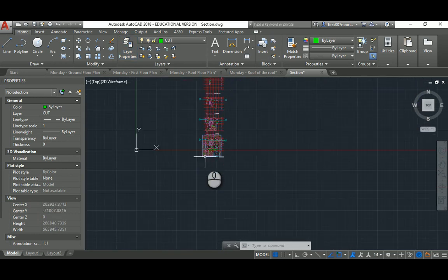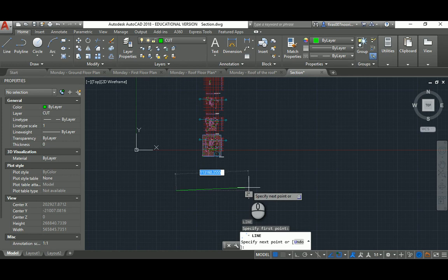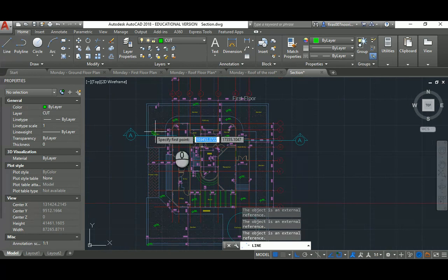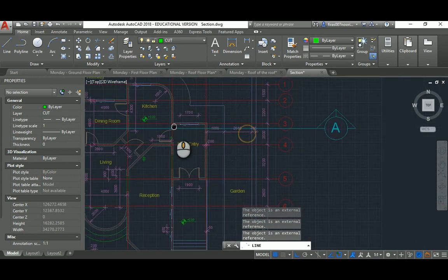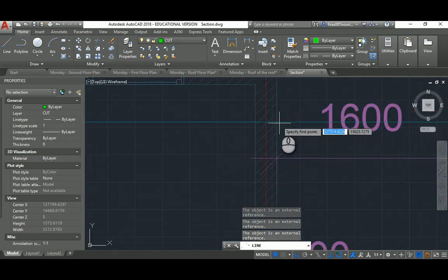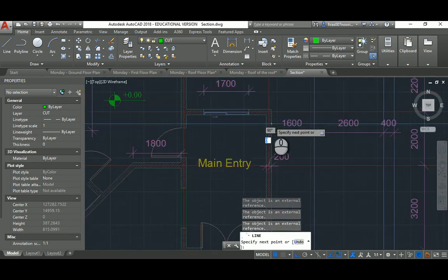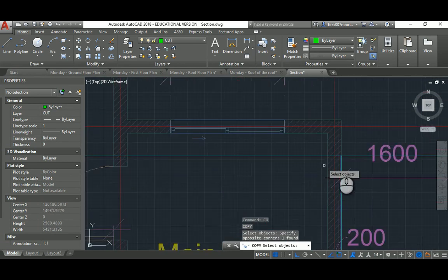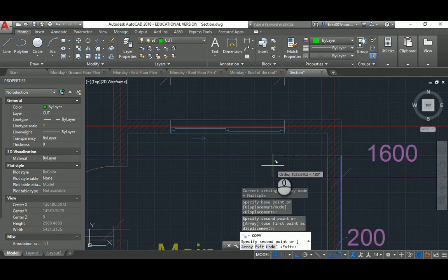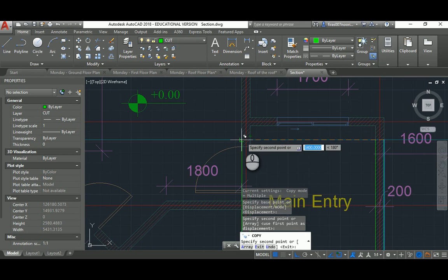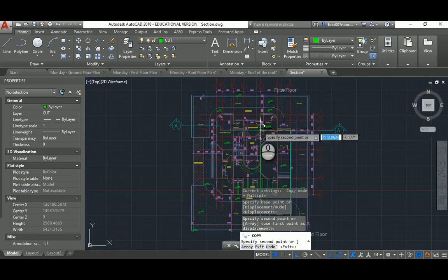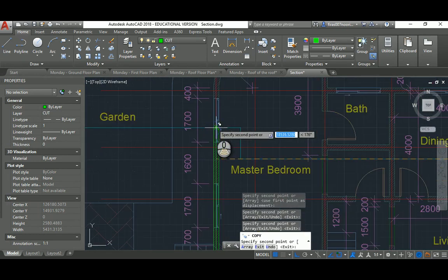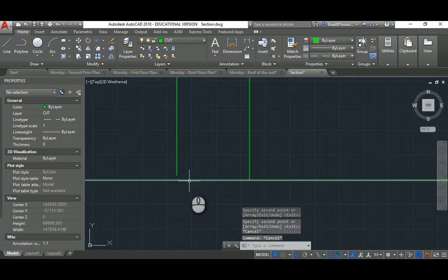Anyway, so I'm gonna just draw a line here. Probably I need F8, and in this case you have to follow and trace the section line, of course, wherever it cuts the building. And in the beginning, that's the technique that I use, which is just to cut the external shell of the building just to define the external boundary of it. I totally advise you not to trace everything, not to cut everything inside. That's going to be confusing. Just draw the outside of the building as such. That's what you see, the shell without the openings. That's my way of working here.